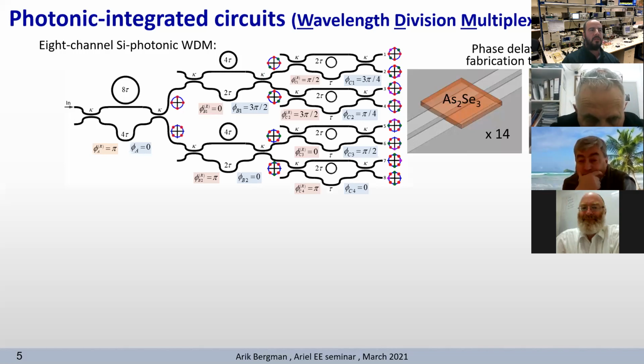We deposited patches of a thin layer of chalcogenide glass on top of the silicon waveguide. Then we selectively illuminated these photosensitive upper cladding layers with an intense laser beam in the near infrared. This results in a chemical reaction known as photodarkening, in which the refractive index is increased. Or the layer can be completely removed in the process of mass transfer if the intensity of the laser is high enough. We control the exposure by monitoring the filter's response and comparing with the model.